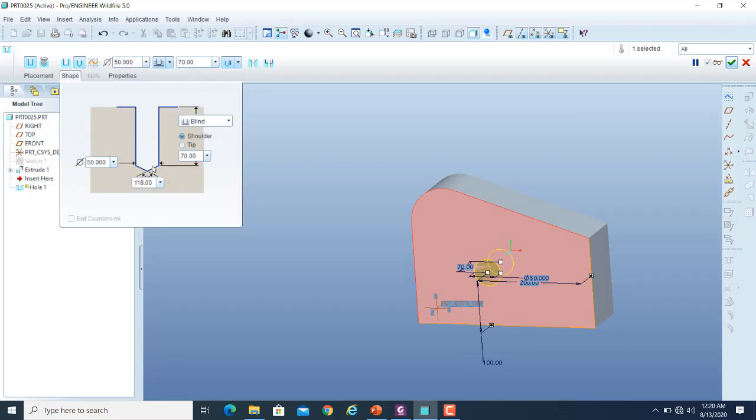So you now look at the cross section. For example, so if you really want to machine that whole feature within the block using the manufacturing module, so वहाँ पे हम twist drill use करते हैं, ठीक है ना. And twist drill का अगर आप point देखें, so that is conical in cross section, and normally the standard angle is 118 degree for that. You can change that angle also.